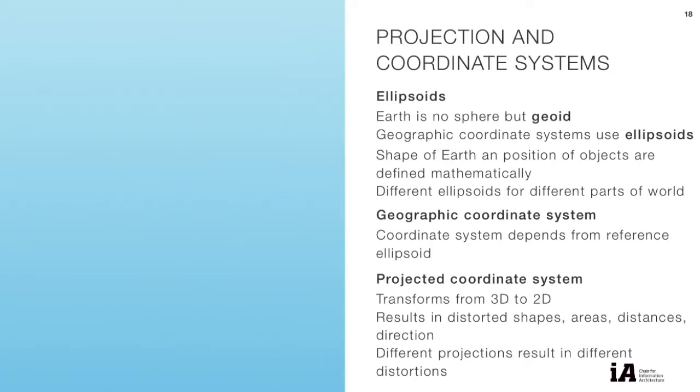Even on a city scale like Zurich, you already have effects. If you want to make precise calculations, you always get the problem. If you don't recognize that problem, you have shifted angles and messed up areas, because different areas are reported than the real ones in the real world. So you need to use a geo-information system at the latest at this point, because it's a system which can handle it.